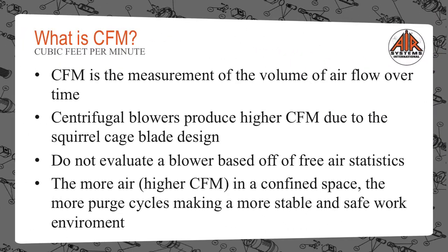What's CFM, you ask? CFM is the measurement of the volume of airflow over time. This is important because if you need a large volume of air in a long ducting run, then a centrifugal blower is a better option based on the CFM at distance the blades can produce. Why can the centrifugal blower do this?